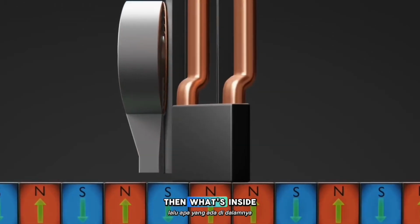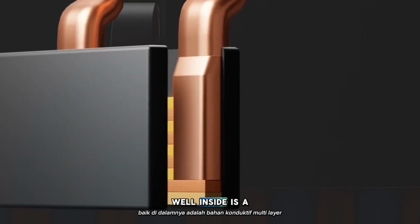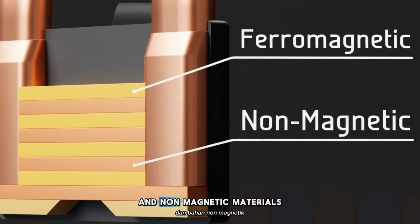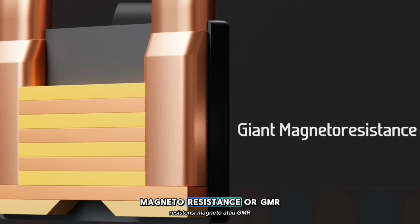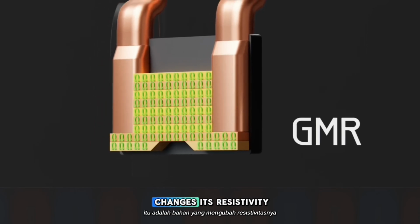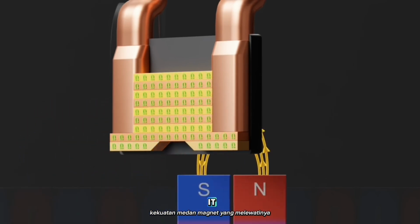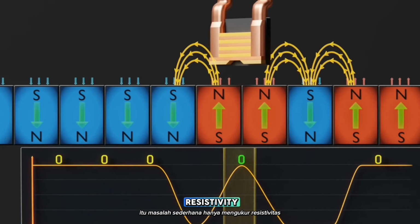So then, what inside the red hat detects these magnetic fields? Well, inside is a multi-layer conductive material composed of alternating layers of ferromagnetic and non-magnetic materials. This multi-layer material has a property called giant magnetoresistance, or GMR. And put simply, it's a material that changes its resistivity depending on the strength of the magnetic field that passes through it. Therefore, using GMR is a simple matter of just measuring the resistivity.